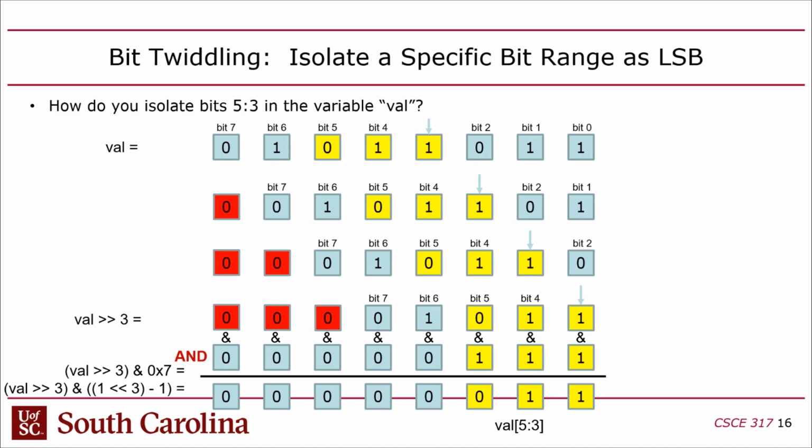Okay, so then what do I use that for? Well, in this case, I'm just using it to mask. Because if I AND with 111, it's going to 0 everything except for the 3 bits on the right, where that 111 is. So hopefully I answered the question. So that's the difference between single bit versus multi-bit. It all has to do with that temporary register that you're going to use as a tool.